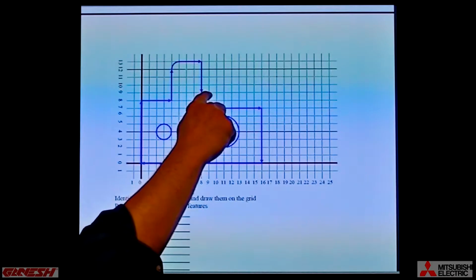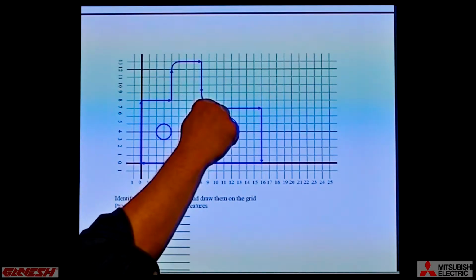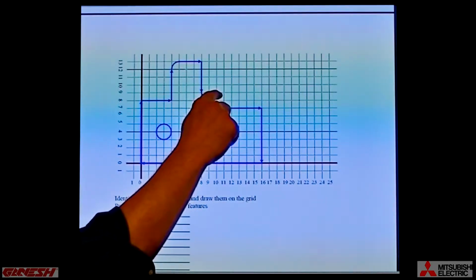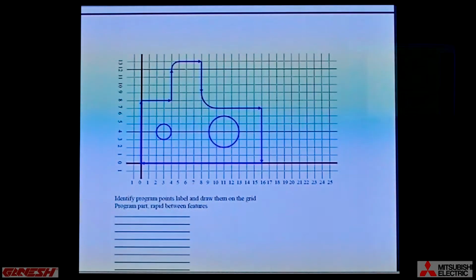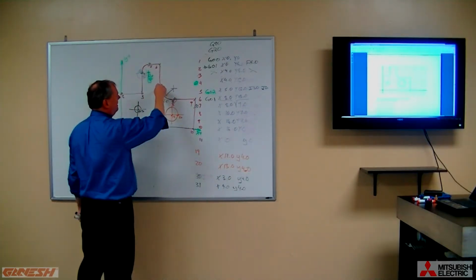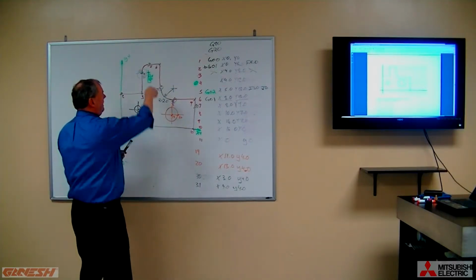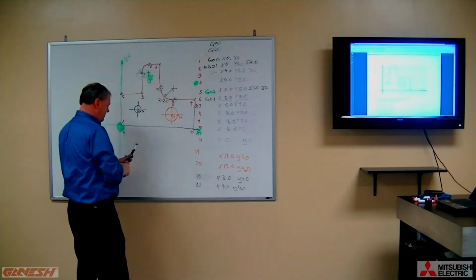It begins there, so it's 2 over and 2 up. So it's a 2-inch radius, and its point is at X plus 2 from our temporary location, right? So if the cutter's sitting here, we're 2 inches over in the X plus direction, and we're at the Y0 direction. So is this a clockwise or counterclockwise move?